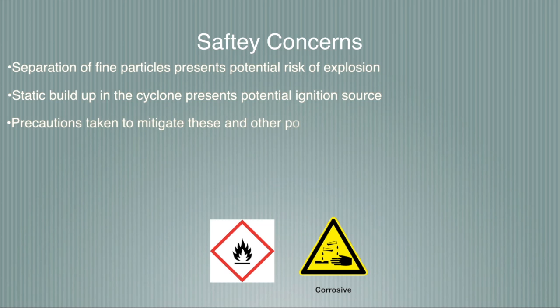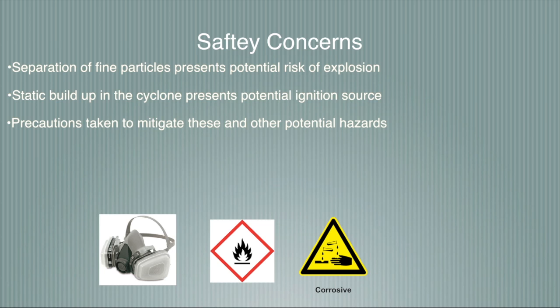Safety precautions need to be addressed to mitigate hazards. For example, the issue of fine dust particles in the air. Personal protective equipment like respirators can be used. Suppressants are also commonly used before or within a cyclone to decrease the chances of ignition or explosion. Most of these risks are associated with industry. Our main safety concern was with inhaling the escaping particles.